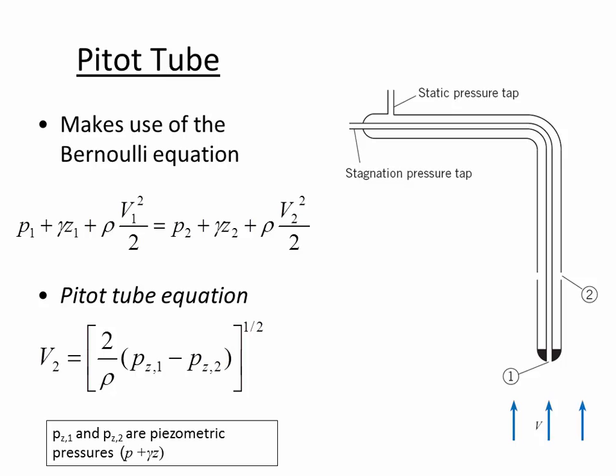And then what this Pitot tube does is it takes the pressure at another location so that it can be differential. So instead of measuring the pressure relative to the atmosphere in an inconvenient way, like the stagnation tube was, the Pitot tube takes a sampling of the atmospheric pressure very close to the stagnation opening.